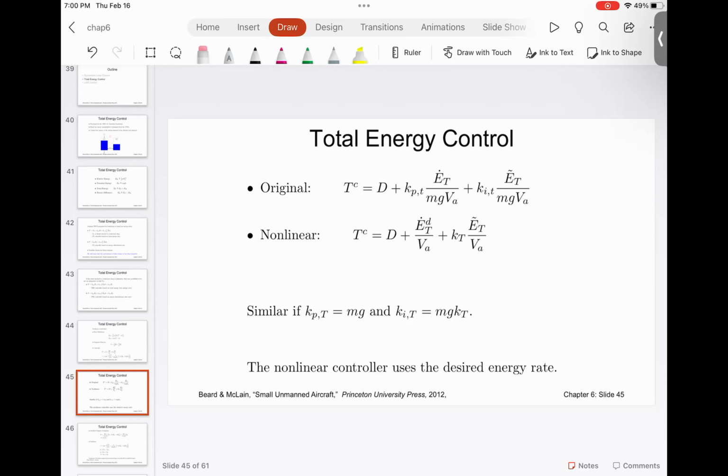Because if you have a function like sine theta or cosine theta, please understand, the computer does not know sine theta, does not know cosine theta. It evaluates sine and cosine theta using some type of successive approximation. That approximation should be accurate enough in the teeny tiny time that you have to complete that calculation, so that the value from that approximation matches the actual value. That is where the difficulty lies. Okay.